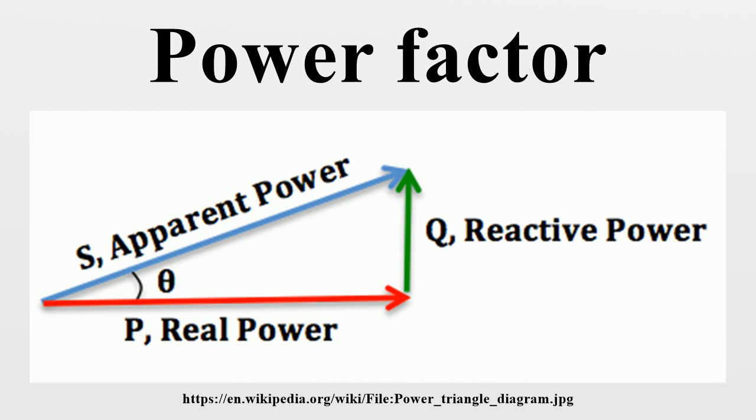A high power factor is generally desirable in a transmission system to reduce transmission losses and improve voltage regulation at the load. It is often desirable to adjust the power factor of a system to near 1.0. When reactive elements supply or absorb reactive power near the load, the apparent power is reduced. Individual electrical customers who are charged by their utility for low power factor may install correction equipment to reduce those costs.